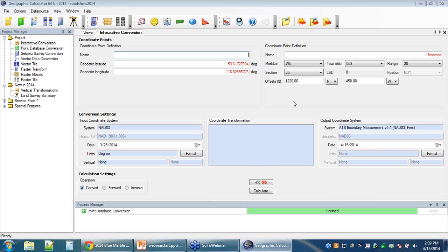All of the coordinate system controls are going to be the same from job to job. So you're going to see these controls down at the bottom here, the blue boxes, where we set up our input and output systems. Things like a latitude-longitude system as we have here, just a basic latitude-longitude on NAD83. Any of those geodetically based systems, projected systems, if you're going to be using things like UTM coordinates, or the MTM systems that you folks use up in Canada, anything like that is going to be able to be used right on this interface.